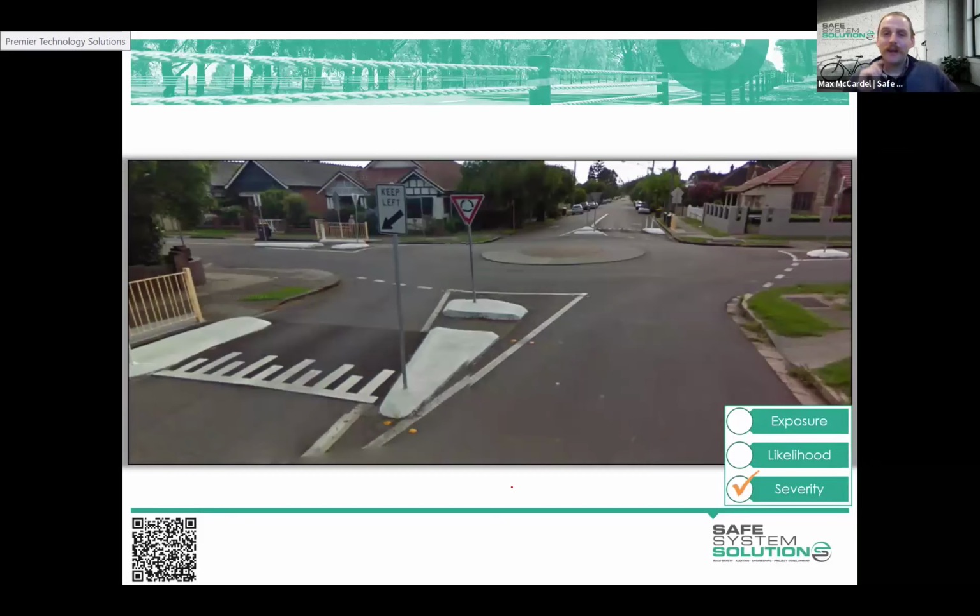Another thing that we can see with roundabouts to further reduce speeds is the idea of actually incorporating vertical deflection on approach to the roundabout. So if you're unable to get enough speed washed off or speed dropping just due to the radius of your curves, well, you can implement vertical deflection, speed humps, speed cushions, things like that. So you're physically slowing down vehicles before they get to that comfort point. Once again, this is a local example, may not be appropriate for what we were looking at before.